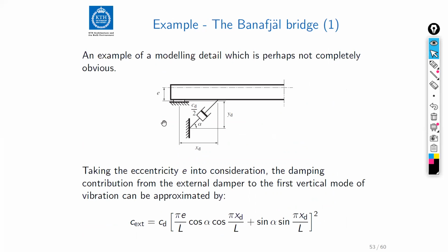Another way of dealing with this is ongoing research now here. Maybe you have met Sara Tell. She is a PhD student here at KTH, working for Raed Karoumi, and she's working on this particular problem. Instead of mounting this TMD, the point with the TMD is that we tune it to a certain frequency. So this needs to be maintained. This will detune itself over time, over 20, 30, 40, 50 years. So if you put a TMD, you also have to set up a maintenance scheme for that, and you have to make sure that it's actually followed.